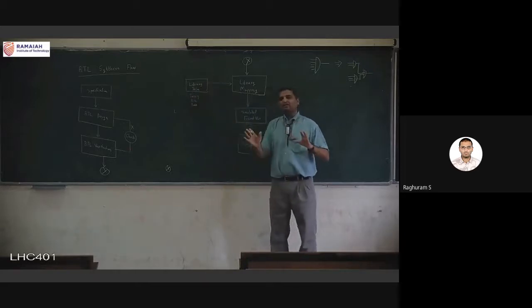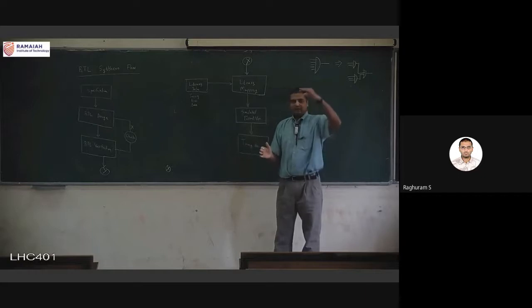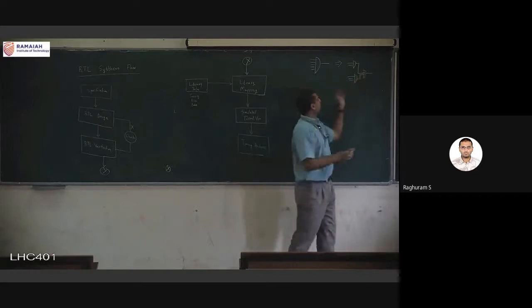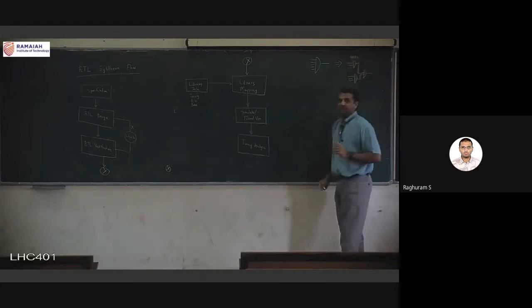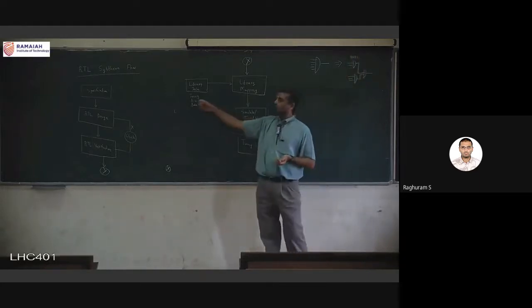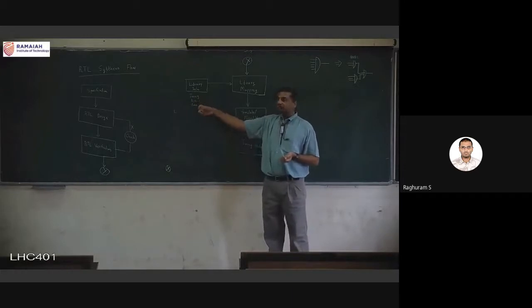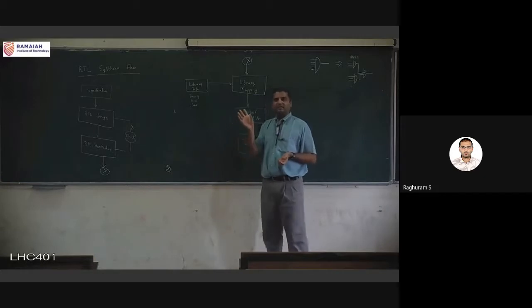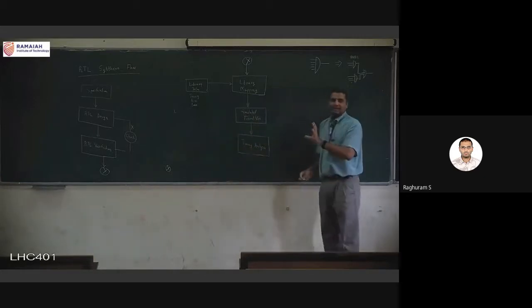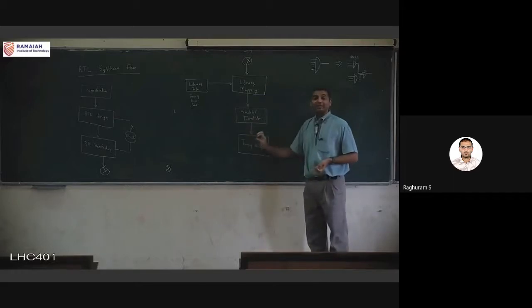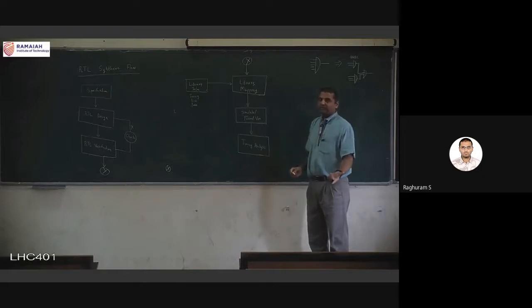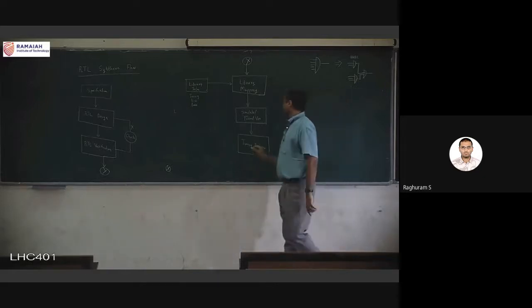Library data is nothing but a text file. It will have the name of the gate, so for example, this might be AND 2. It will have the area of the cell, the timing information, and the power information, and this is all written inside a text file, and that is the library data. And once we have the library mapping and this, we can do a timing analysis for the first time. And again, if it is not satisfied, we have to go back.